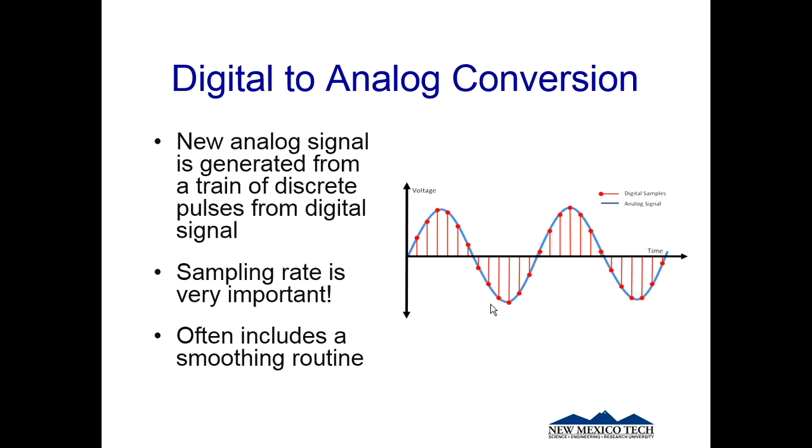We can also go the other way. Suppose we want to send a control signal out to a valve. Well, we've generated a digital signal in our computer, and we're sending it to something that's going to control a flow rate. Well, as it turns out, that might not be as simple as we think, because we only have certain values. So that's what this whole problem is going to be in instrumentation: dealing with how we take an infinite number of states, convert it to a finite number of states, and then how I send a control signal that's a finite number of states and make it act in the real world where it's an infinite number of states.